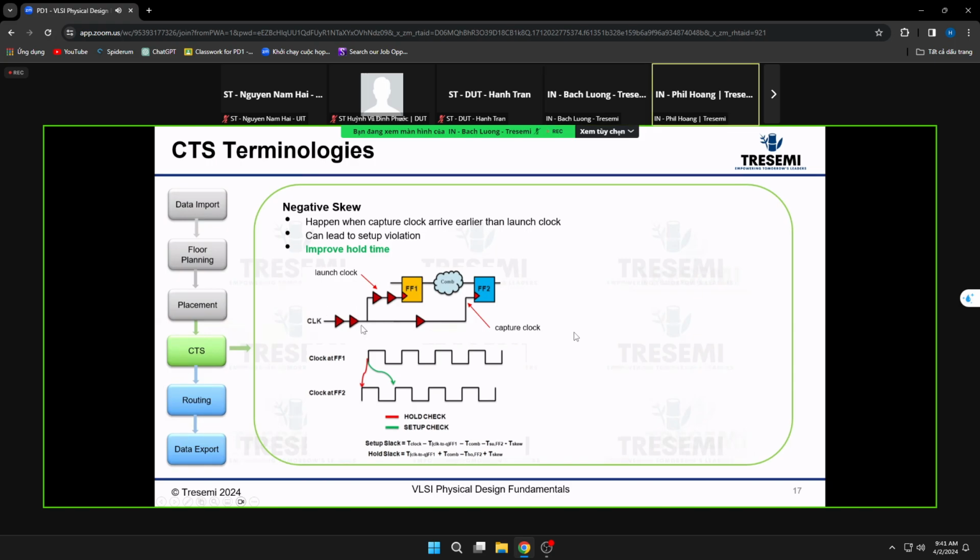But can you mention OCV for that CRPR? I think that's related to OCV. Phil, you can go ahead if you're thinking about it. Yeah, I think the CRPR is related to OCV, on-chip variation. On-chip variation adds extra delta delays on each and every gate.